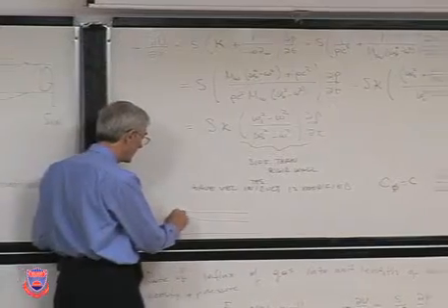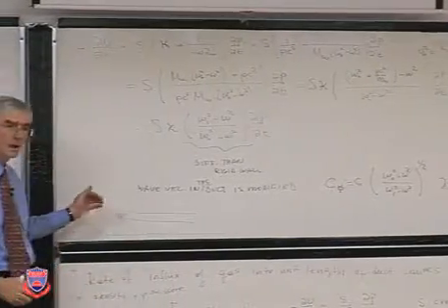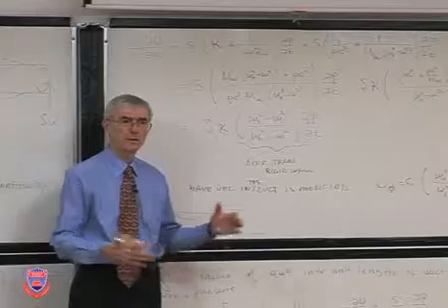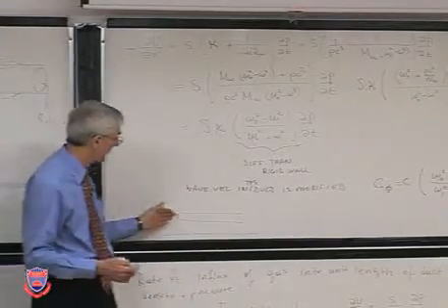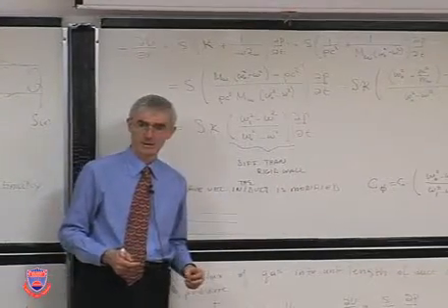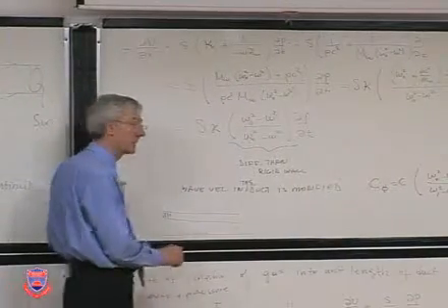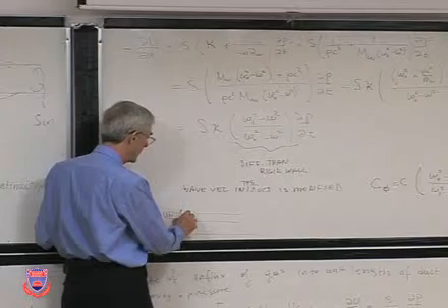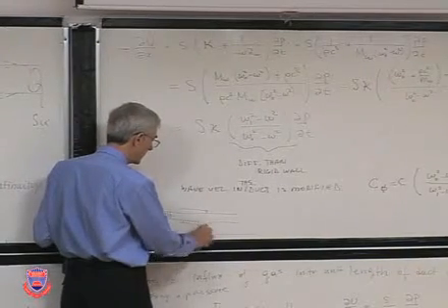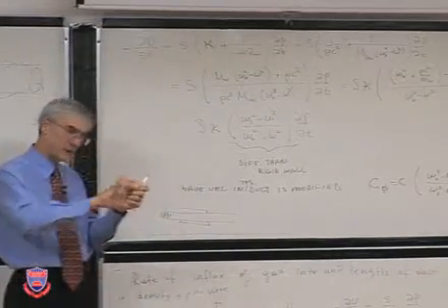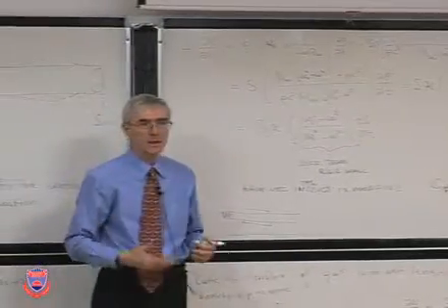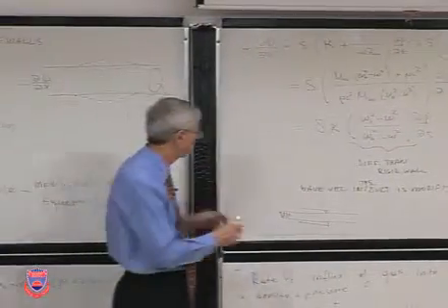So you have these very strong pressure pulses generating huge amount of vibration and noise that transmit through the pipe. And one thing that can be done, and that is being done, is you put around it a sleeve with, say, a liquid, okay?